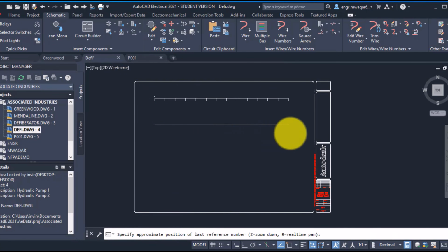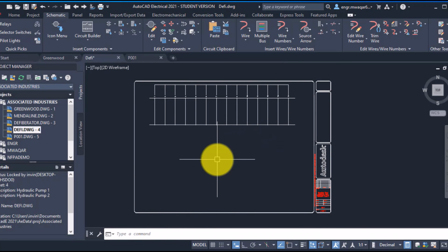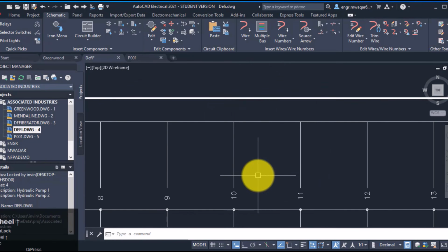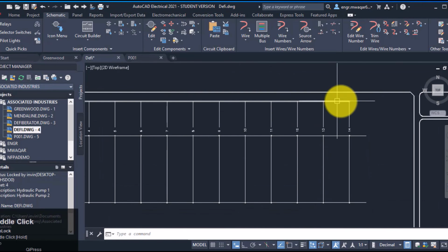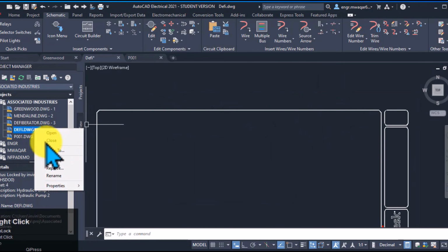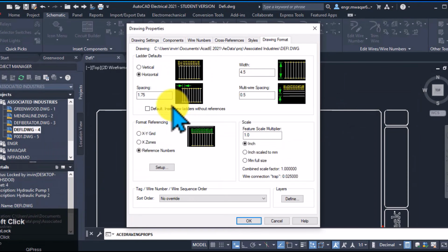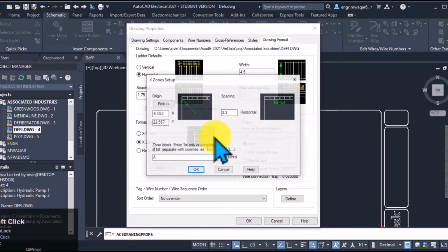So the pro tip here is always turn on the labels first. And that naming convention, the CRB4, that is the smart connection between the grid and the component, right? Yes. In AutoCAD Electrical, a component's name, its tag, is essentially its physical address.